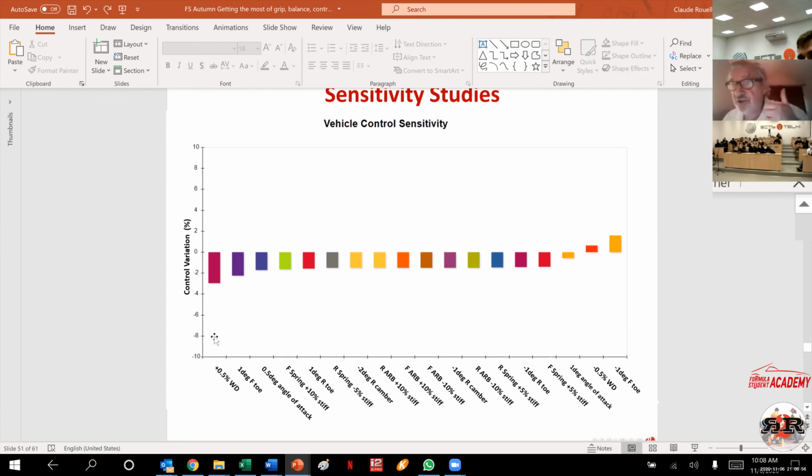And in the differential, you have 3 things you can change. You can change the preload, you can change the ramp angle, and you can change the number of shims, the number of active plates that you can have. So it's a long answer to kind of excuse or justify the reason why the diff is not there. But absolutely you should do it.